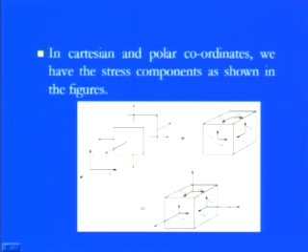The triaxial part is there, in which all three stress components are there in x as well as y as well as z. So if you are working in the Cartesian coordinate system, then you can see here these are my three different normal stress components. See very carefully here, we are only considering the tensile stresses because they are all going towards the outward direction. So here sigma x is in the x direction, sigma y is in the vertical direction, and sigma z is exactly in the z direction. So these are my normal stress components, which are well set up within this unit cube.